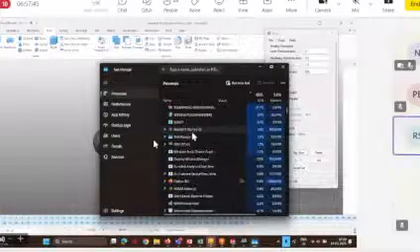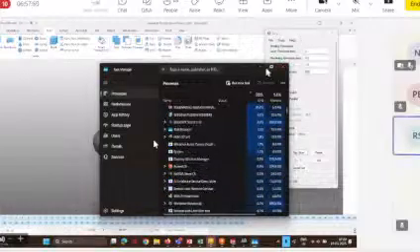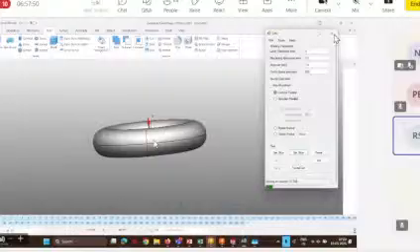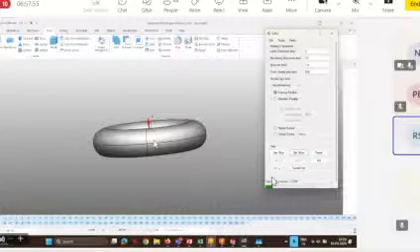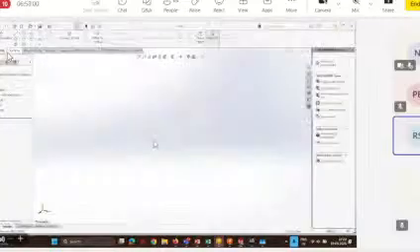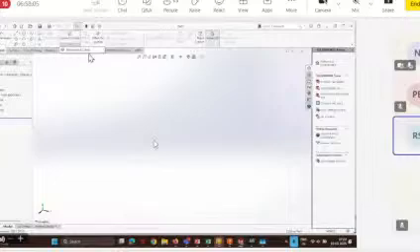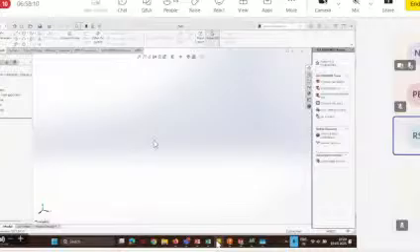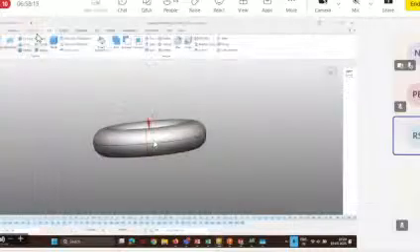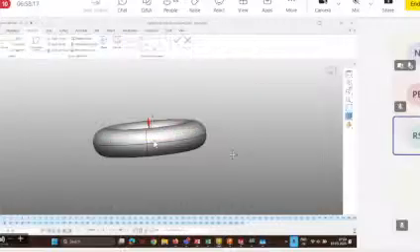Okay, it just hung actually. So all right, by the time it is fixed, I'll just show you the same thing we can see in SolidWorks. If you go to the sketch and go to Convert Entities, insert this one, you can see this intersection curve. The same tool that I've shown you in PowerShape inside this wireframe tab only. So the same thing you can use over here.